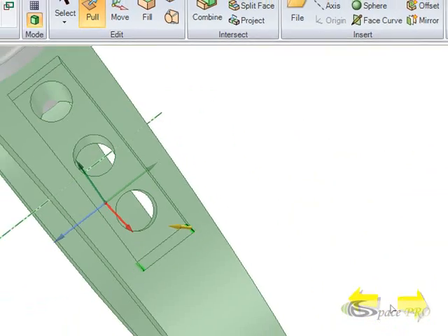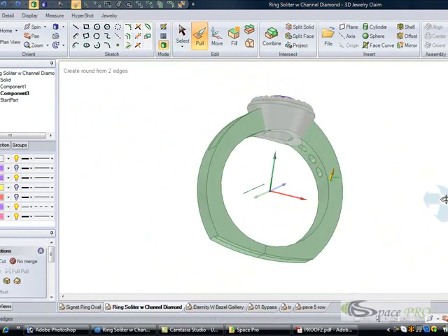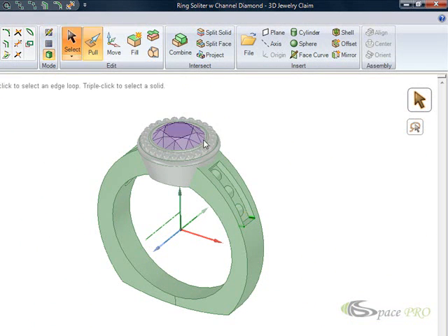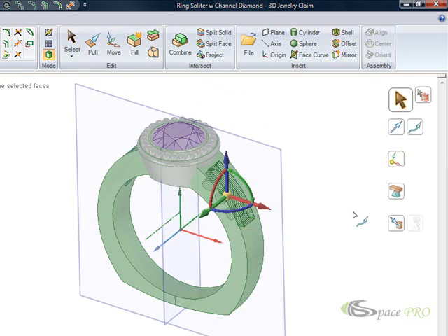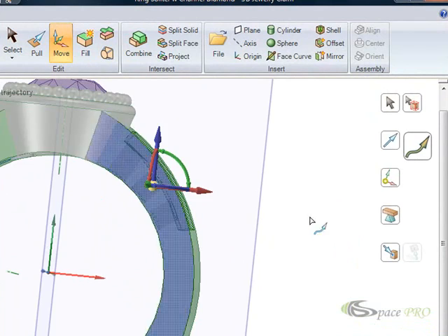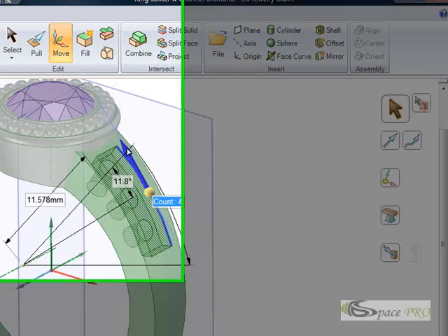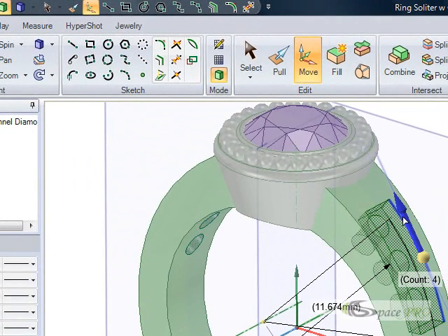or not, go back. And one more, we can shell inside the ring completely if I need, or I can select the whole channel by moving. Since it's a cathedral style ring and the thickness in here and here is not the same, I'm going to grab this line over here and move the channel with the line a little bit lower on the side of the ring.